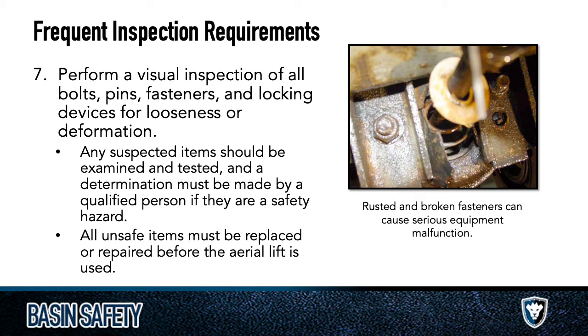Again, it's like before, right? If the instructional markings in the man basket, where you have your controls up there, are starting to get a little sun faded, but you can still read them, something to note, maybe you don't need to shut the whole job down. It's a little faded there, we probably need to get a new sticker. But if hydraulics are leaking, and you start to go up and you're bouncing around like crazy, probably time to shut that thing down and take it back to the yard.